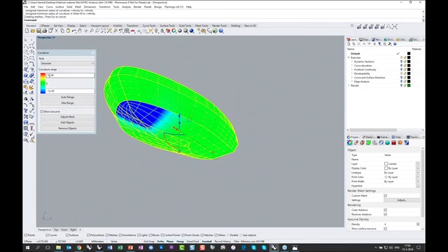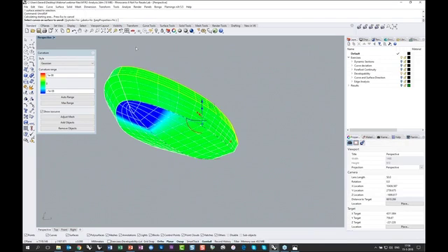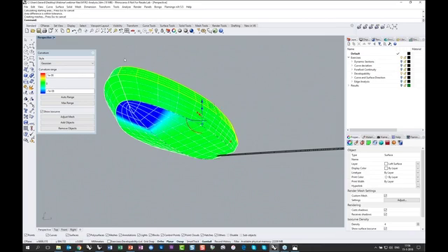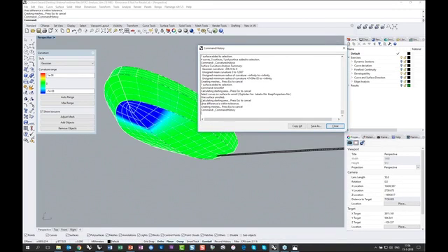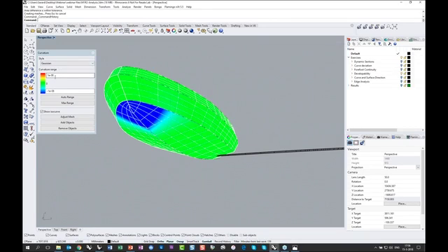the setting over here depends on the size of the ship. And what I found out is that I just play with this setting, and in the end, most important is when I unroll this surface, Rhino gives me feedback over here about the accuracy. And this is for me most important. So the setting is important, but it's not an absolute setting. It's relative. Depends on the size of the ship.